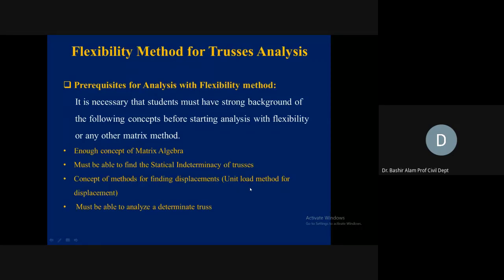So here you cannot afford taking joint by joint for the analysis of each member, because that will take a lot of time. So most of the members you should be able to analyze by observation. And in some cases, if you need the method of joints, you can apply, but for the whole structure, for all the members, it will become very time consuming.